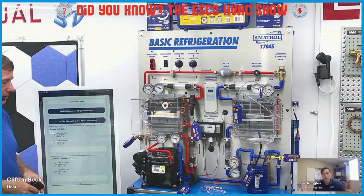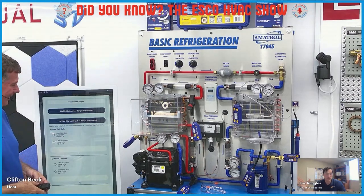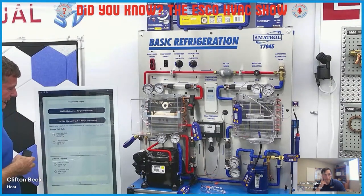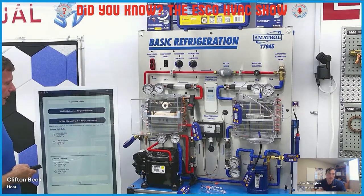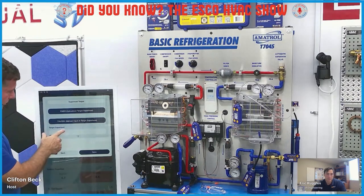It'll calculate it. Nameplate is based on specific conditions, right? Yeah. But if it's an extreme condition, those superheat numbers are going to be off, right? So you want to use it for the actual conditions. You can do it calculated based on a fixed value. That's fantastic. Yeah, because depending on the metering device, that's going to be quite a variance. Exactly. But obviously, for a TXV or EXV, you're going to have to put it in because that's going to auto correct for you.